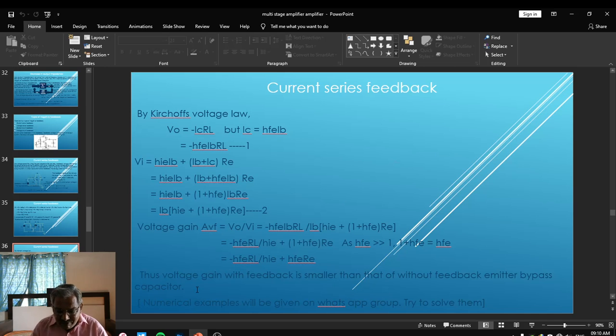Then we have studied the advantages and disadvantages of negative feedback amplifier. After that, we have proved by using negative feedback how stability is increased, how bandwidth is increased, how impedance is increased, how noise is decreased, distortion is decreased, and also how output impedance is decreased. By studying the respective advantages, we concluded that it has only one disadvantage, and that is a reduction in gain.